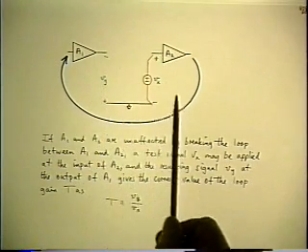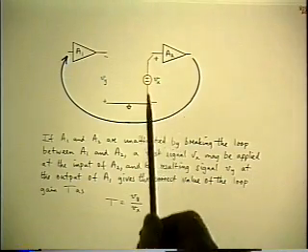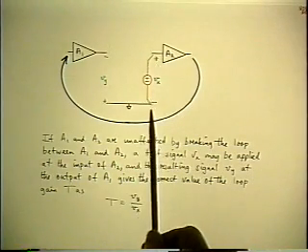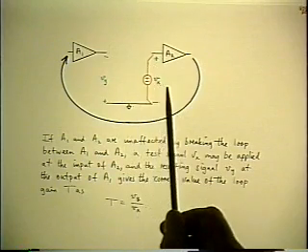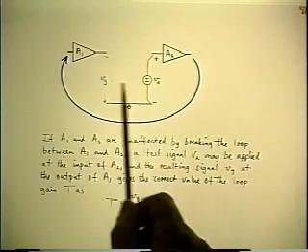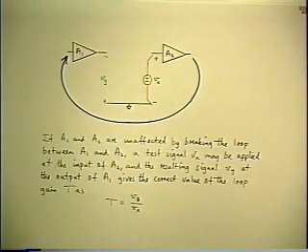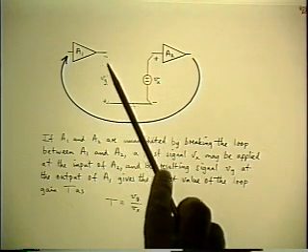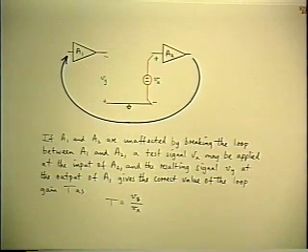So when you break the loop, the first thing you have to do is reestablish the operating point, and it takes a very fine resolution, regulated power supply to do that. And even so, you spend half the time twiddling that knob and adjusting it so the other end of the loop, which is wandering around because of temperature sensitivity and gain variations, it's hard enough even to keep it in the active range, never mind at the right operating point.